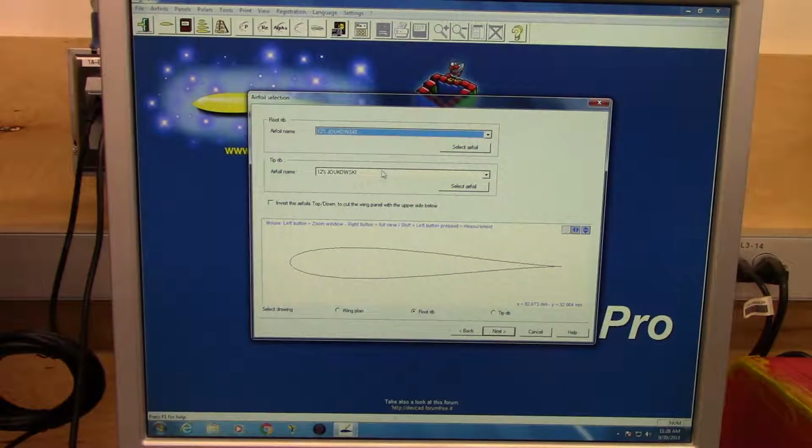I should also note here that although wing twist will also change your airfoil slightly in the middle, as long as you have the same airfoil for both your root and your tip, and you have a reasonable washout of only a few degrees, then the effect in the middle of your panel should not be significant.